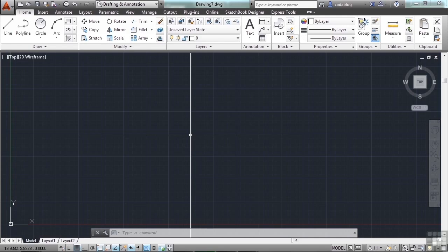If this is done properly, then AutoCAD can interpret the different units accordingly and scale the line work as needed when you bring it into your drawing. Keep in mind that not all CAD users are created equal, and none of them are as responsible as you are, and they may not have properly set their units. So it's a good idea to check the file before you work with it.